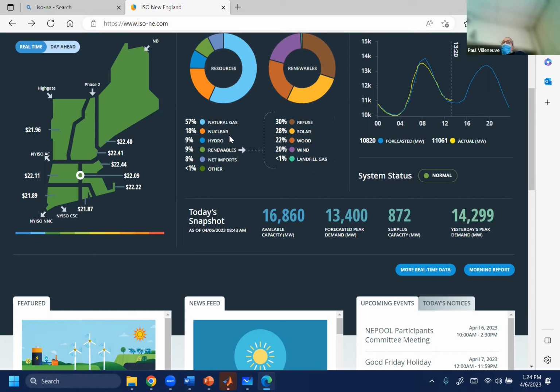They're actually designed for the size of these containment vessels, and inside containment, they have a loop with water. And if one of those lines break, all the water that's in the reactor dumps out. You have this instantaneous change in pressure because the water lines are running at 2000 PSI at 600 degrees. All of a sudden they're at ambient with no pressure. So inside containment would go to like 55, 60 PSI. And those containment structures are designed to not get damaged and only leak a certain amount.